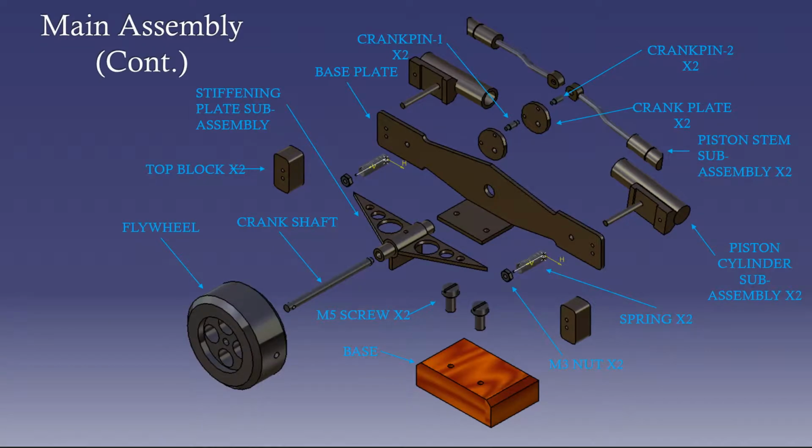So this is the exploded view for the twin boxer steam engine, and as you can see, all 20 parts and 3 unique subassemblies have been outlined. This assembly was very challenging to put together because of some weird quirks with the assembly of the final engine. For example, this piston right here was not parallel to the straight line of the base plate. Instead, it was offset by an angle of, I believe, 15 degrees, so that it would fit on this hole with this pin when this piston was extended.